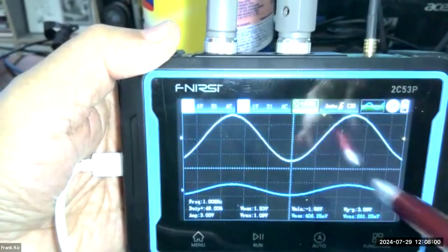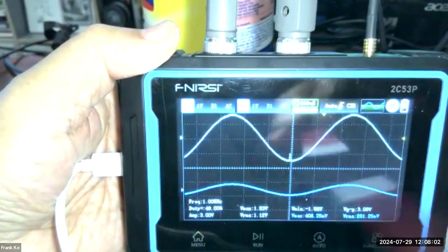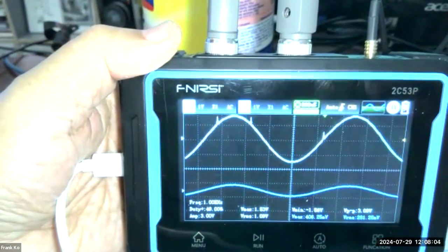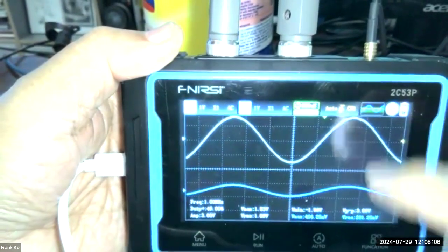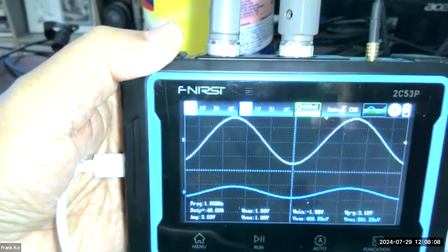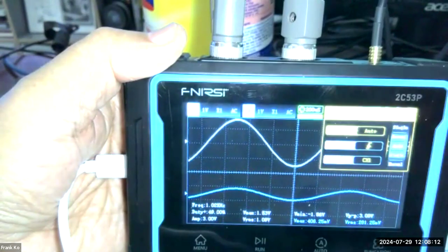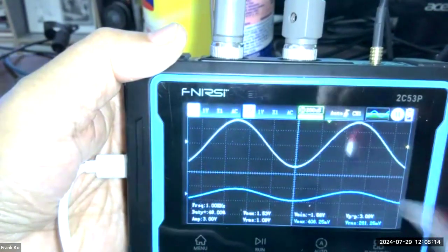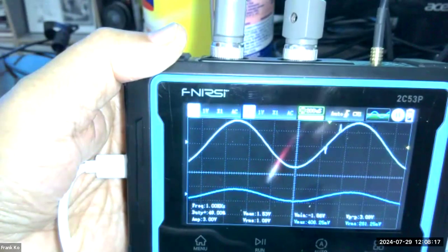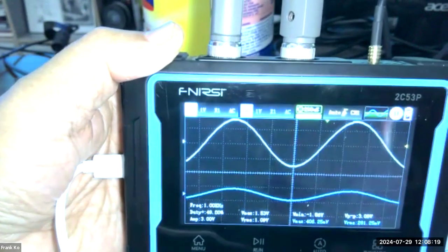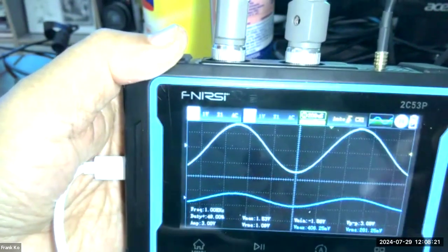What happens is you can see this waveform on point C is quite a bit smaller in size than the input waveform. So the input waveform at 1.5 plus volts peak, and then the waveform at point C, quite a bit less. So we can see dual trace information on here very nicely.